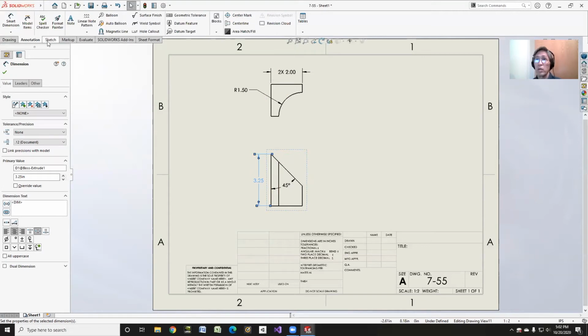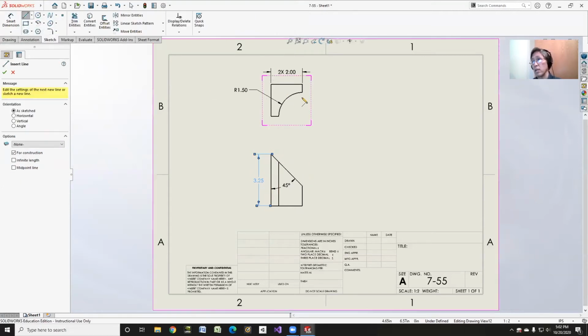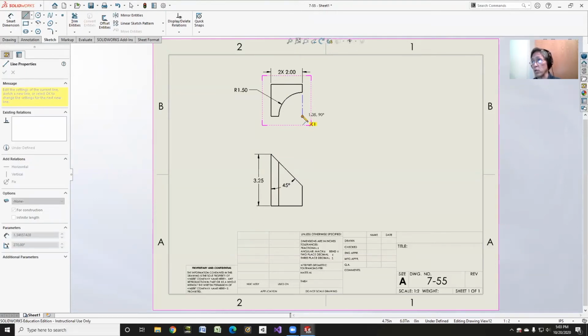Oops, we're not quite done. We want to do a sketch, and we want to put center lines in here. The center lines will locate the center of the circle. So we'll put this down. I don't want to grab the endpoint. I want to grab just off the endpoint. So I'll let that little dash line come there. And I'm going to come just below where that is.